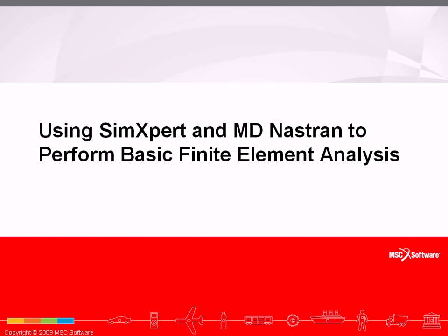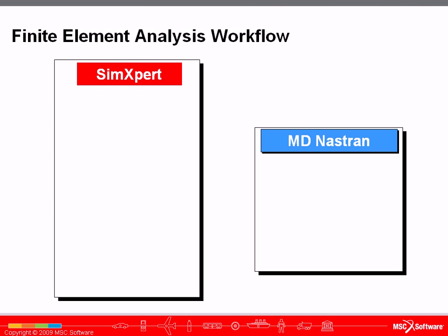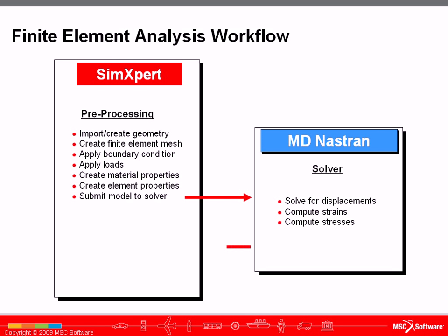In this video, we'll show how to use SimXpert and MD Nastran to perform a basic finite element structural analysis. The workflow between SimXpert and MD Nastran begins with creating your model in SimXpert, then submitting it to Nastran, which will solve for your displacements and compute your stresses and strains, and then you bring your results back into SimXpert for post-processing, where you create your plots and reports.